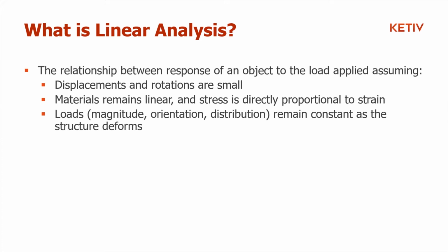But it also means that there's small displacements. Now, small displacements that can vary, right? I can't give you an exact number. What I can tell you is the table we're using right now in front of us. If you put 10,000 pounds, that's a pretty large displacement. I'm exaggerating, I know, but 100 pounds, I would say that's more within the linear analysis range that we'd want to do. Yeah, small and large are pretty relative to the size, the surface area on which the load is actually being applied. So it's always a function of the type of design and the loads that it's actually going to be under. Exactly. Okay, there you have it, and that's linear.